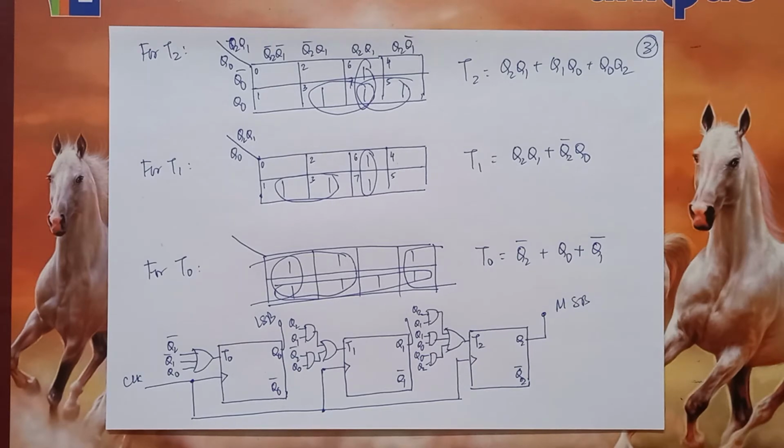Now what was that statement? We had said that while synchronous counters are faster, they demand more logic circuits. They demand a lot more additional gates usually when you compare with an asynchronous counter for the same application. You can see the asynchronous counter, to achieve mod 6, made use of only one additional gate. But here you need about 7 or 8 additional gates, and that is a lot.